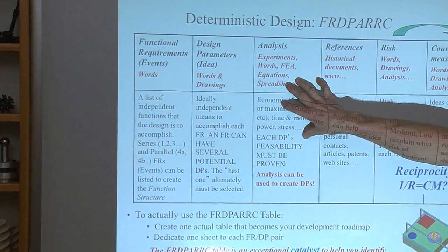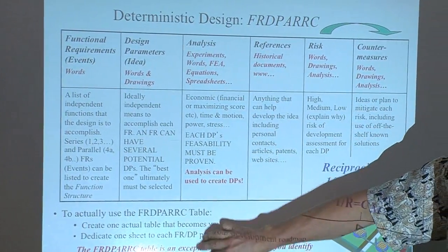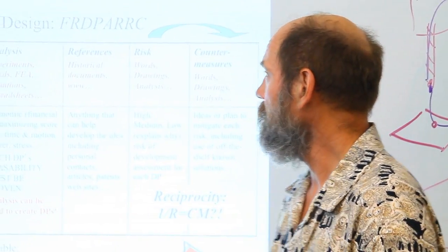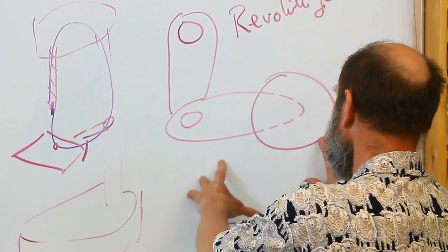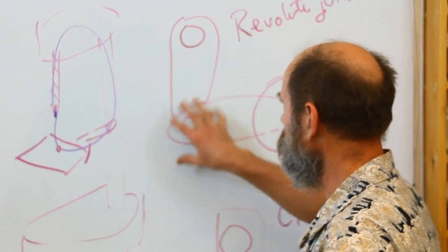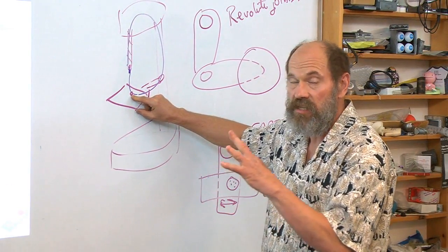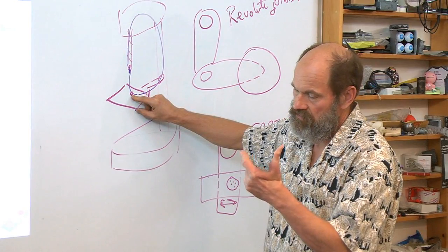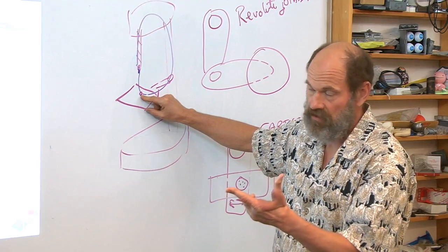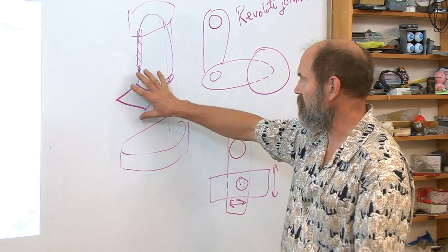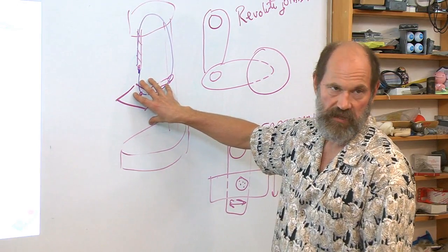And you're thinking, oh my God, physics, analysis, equations. This is where you really make your mark. Because as you're thinking early on, you start doing the analysis of, wow, I've got to move this to move the part on the drill, but how? And there's three types of things. Accuracy, and then you've got repeatability or precision, same thing, and then resolution. Accuracy is if this thing was controlled, how well can you make it go to the position you want? Repeatability would be how well it comes back.